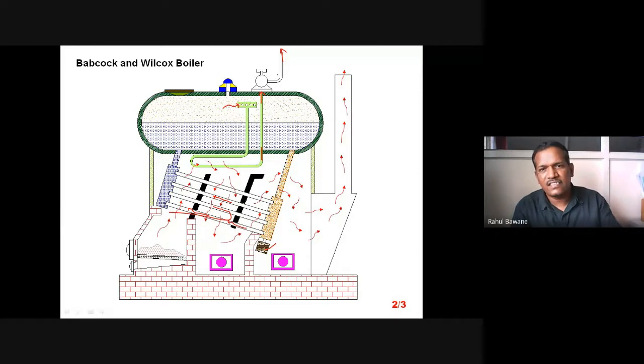So excess heat starts to heat up all the metal parts, and we find that there is a formation of thermal cracks, bending of pipes, and whatever joints are there get leaked. So there is an overheating problem. So always observe what the recommended water level is. For that there is a water level indicator.